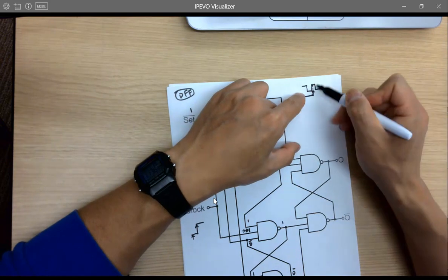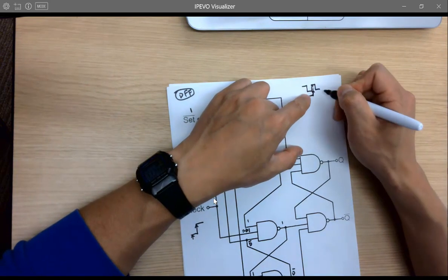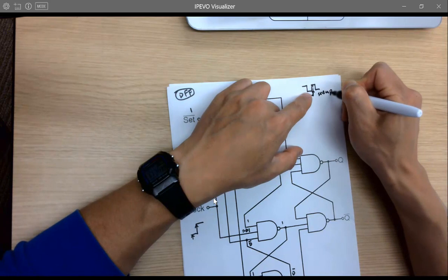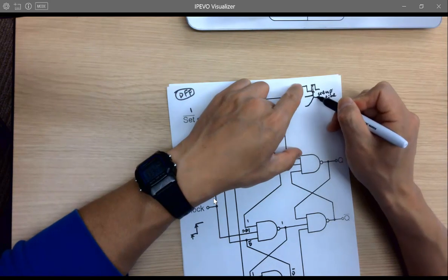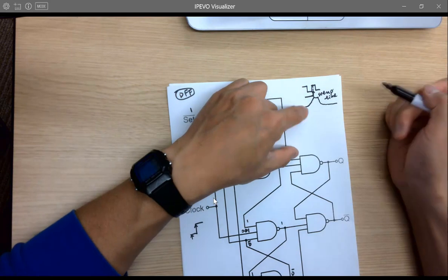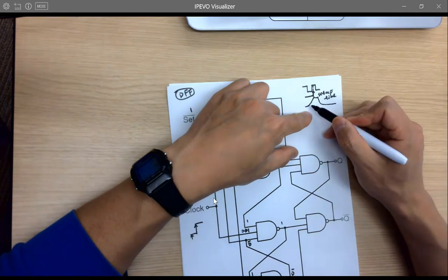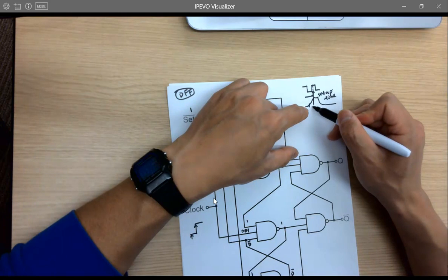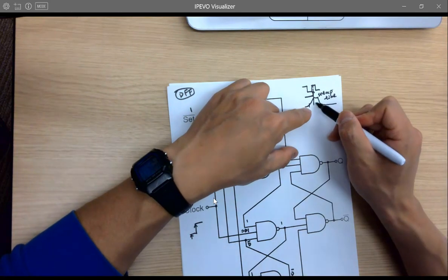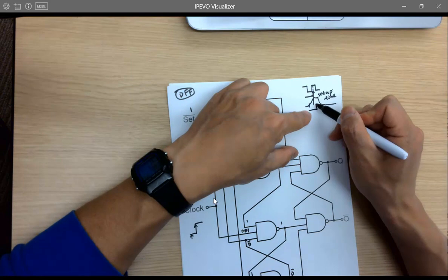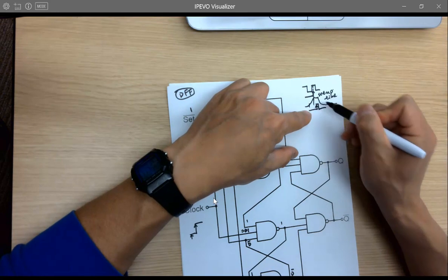So a lot of times for the signal, there's a concept called setup time. Because the signal is very noisy, sometimes getting like this for really fast digital signal. When you zoom in, these are only like a few nanoseconds, so really fast. So you do need some setup time. You need the signal to be ready, and then sample in the middle, right? Here's a clock. A rising edge, sample in the middle.